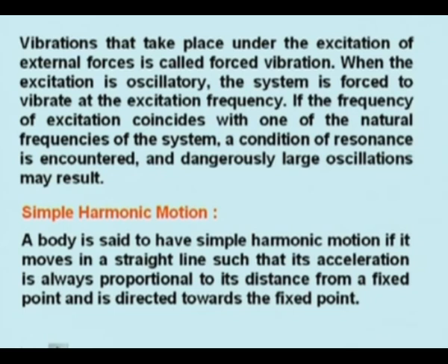In the beginning, the motion can be of some different kind, but after some time the system will vibrate only with the frequency of the force itself. Whatever force you have applied, it will vibrate with that.